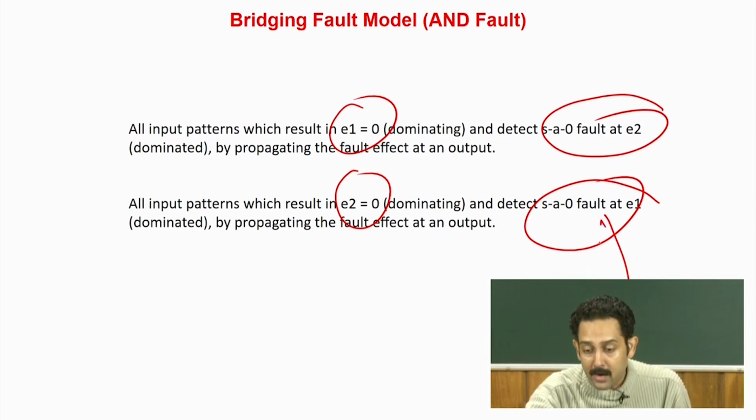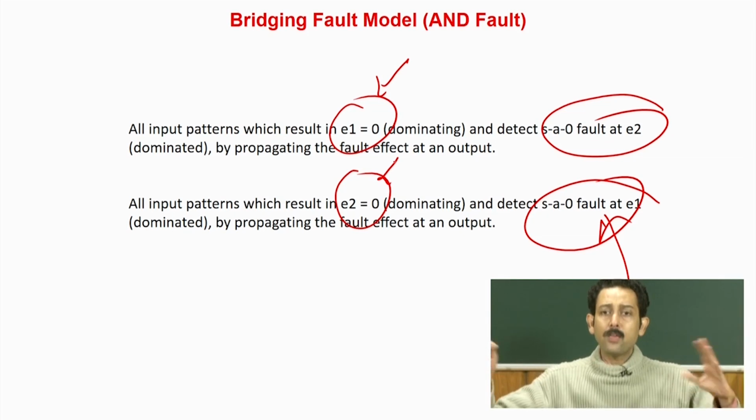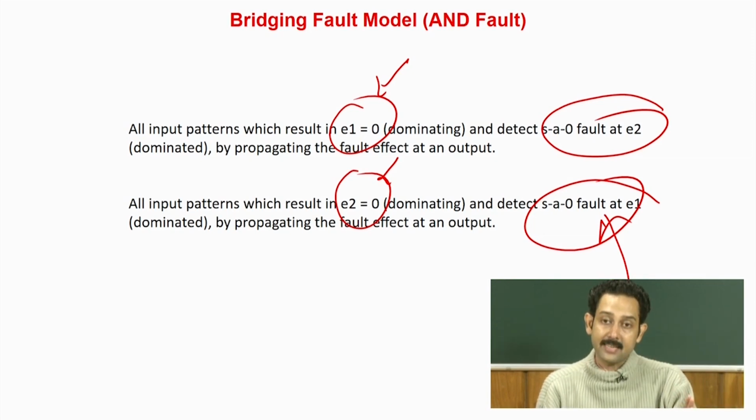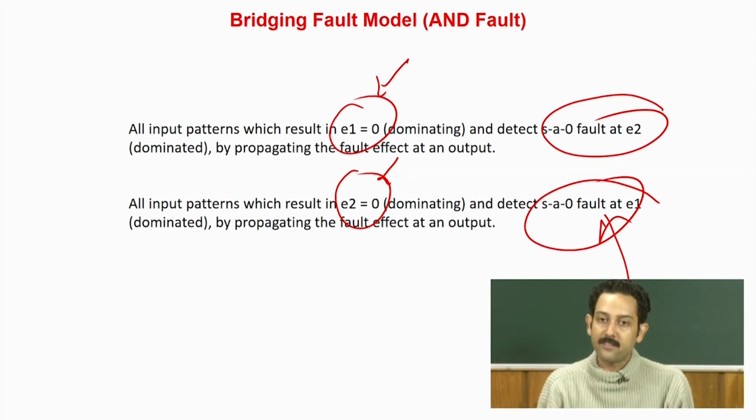So this is anyway similar to stuck-at fault, but this is an additional constraint. If the circuit is very big, you can understand that even adding one more complexity will lead to more amount of time, more iterations, because it is not about just setting another constraint. Setting another constraint means you may have to reiterate, because you may start having conflicts. The more constraints you put, the more conflicts you will have, and more iteration on the test pattern generation rounds has to be there.